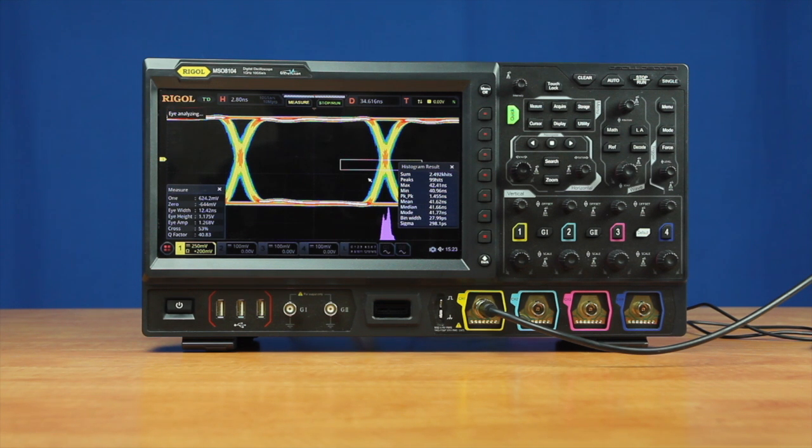So those are the ways that eye diagram testing and a histogram can really help you to complete your signal analysis and signal fidelity measurements by looking at noise, bandwidth, and timing across a complete deep memory cut of measurements and serial data. By overlaying that data from the deep memory into a density plot for easy visualization, the MSO8000 makes eye diagram testing easy.